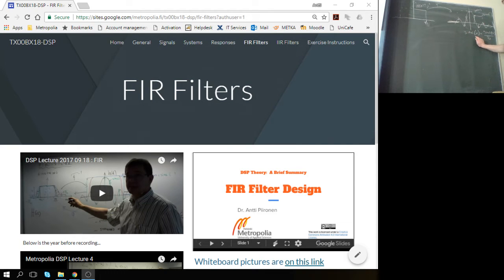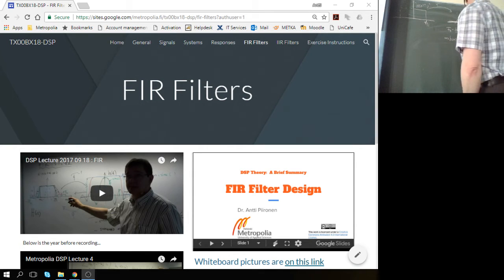And that one sampled. In this case, the exact form, if we have a sample rate fs, 1 over Ts, practically follows the sampled sinc function, which is our h of n, following the sinc of n times the cutoff frequency divided by the Nyquist frequency, where the Nyquist frequency is simply half of the sampling rate.